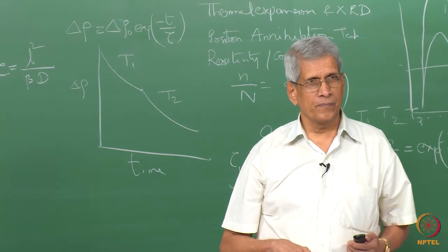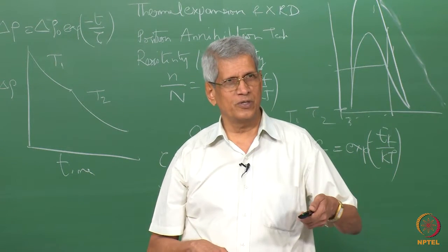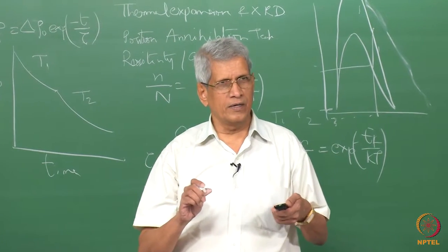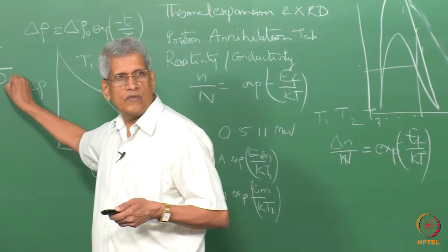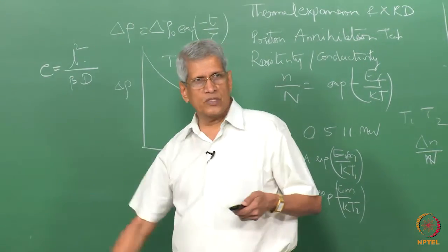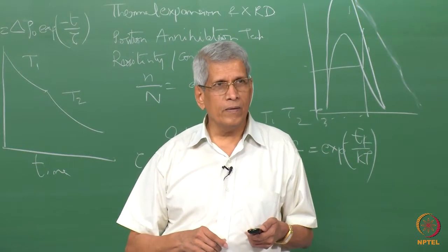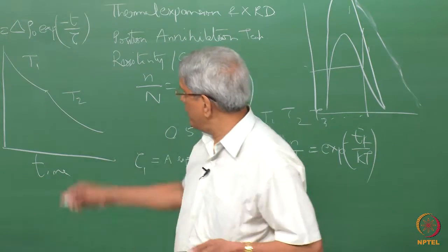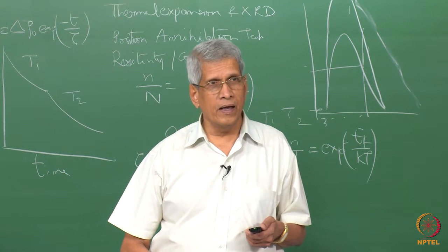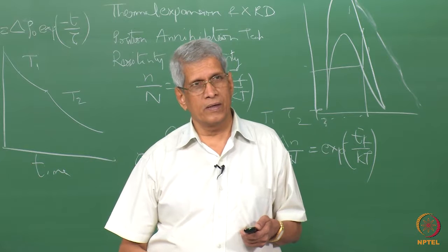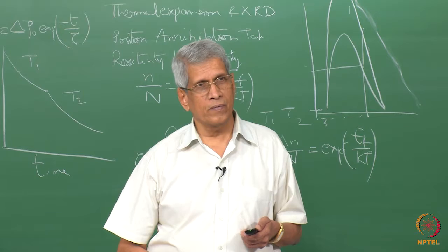Irrespective of the concentration, the rate at which it is going to jump, if the sink distribution is fixed, then L is going to be fixed. Only the diffusivity determines how the tau is getting affected. From that curve, delta rho appears to be a nonlinear function of time. Yes, because this is an exponential function. But we are taking the ratio of the derivatives to arrive at tau 2 by tau 1, so I need to know where I am taking the derivative.